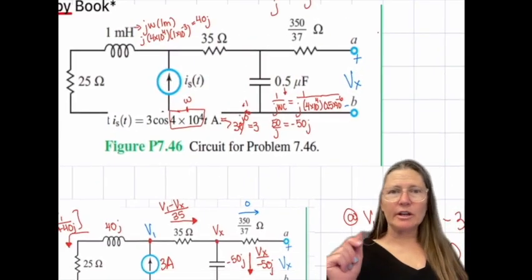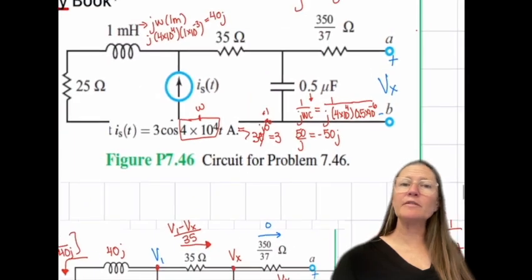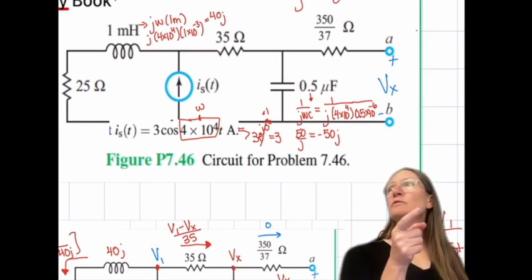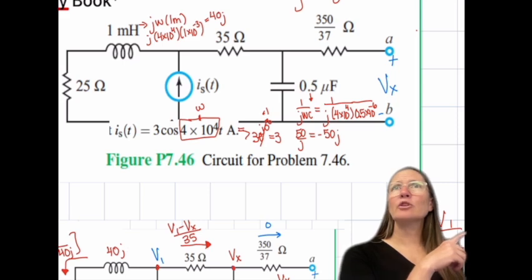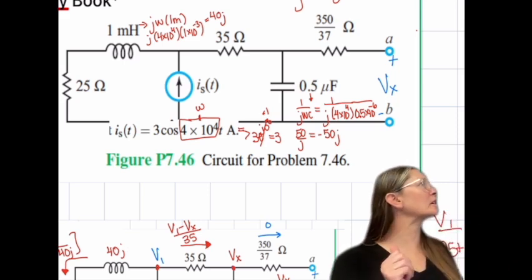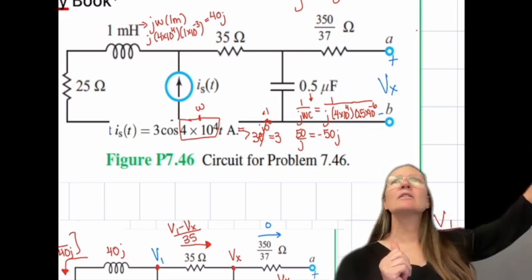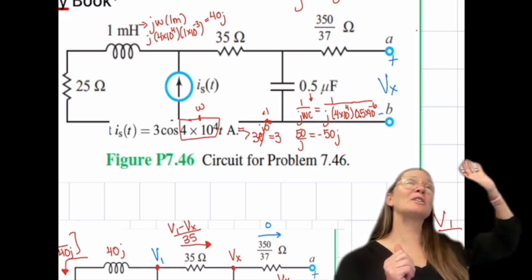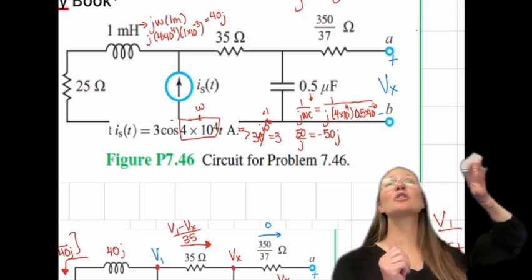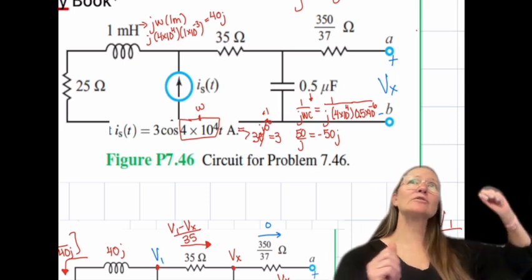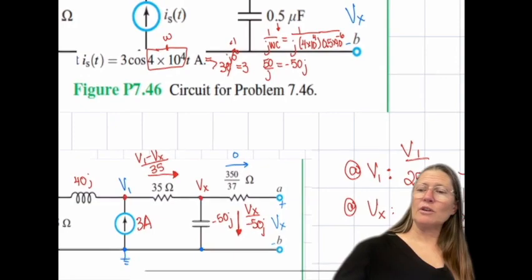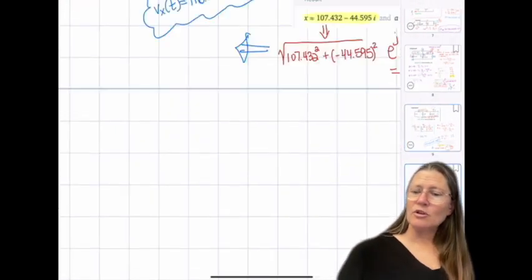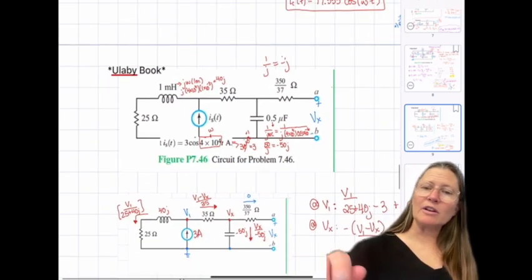One thing to note here is that if you were trying to find the Thevenin equivalent of this circuit, this Vx would be your VTH. So you do this same method as we used before, where you have a location A and B, and now your result for VTH is going to be called ZTH, because it could be a complex impedance that you're solving for.